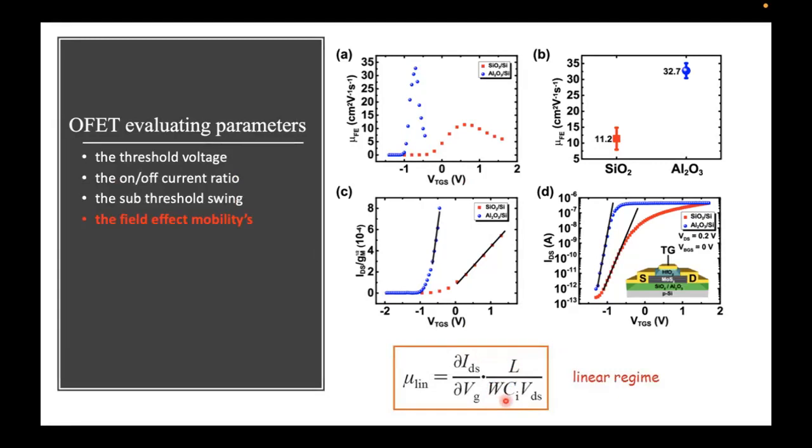But before going further in that, we have to highlight that as our transistors are working in 2 regions of operation, what we call the triode region and what we call the saturation region, then we have to expect that we will generally have 2 mobilities. One in the triode region and the other in the saturation region. In each region, you are using this derivative term between the IDS and the VGS. So using these 4 parameters, we can have a macroscopic characterization for our device.